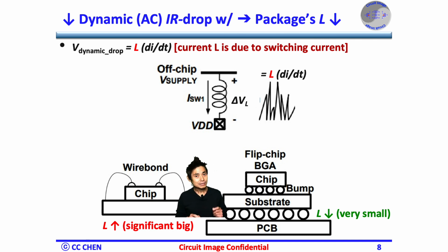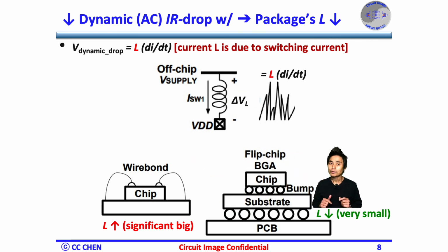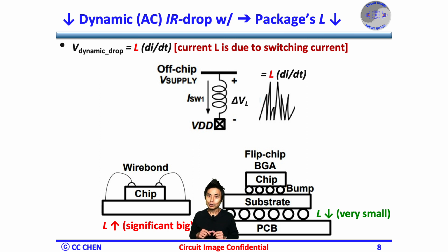Unfortunately, for high-speed SerDes data rate greater than 10 gigabit per second, we must pay a much higher package cost with a flip-chip BGA, which will almost eliminate the inductance. Again, the chip package relates to the cost and performance trade-off. We will just briefly mention it here, and we can talk about the types of package later if anyone is interested.